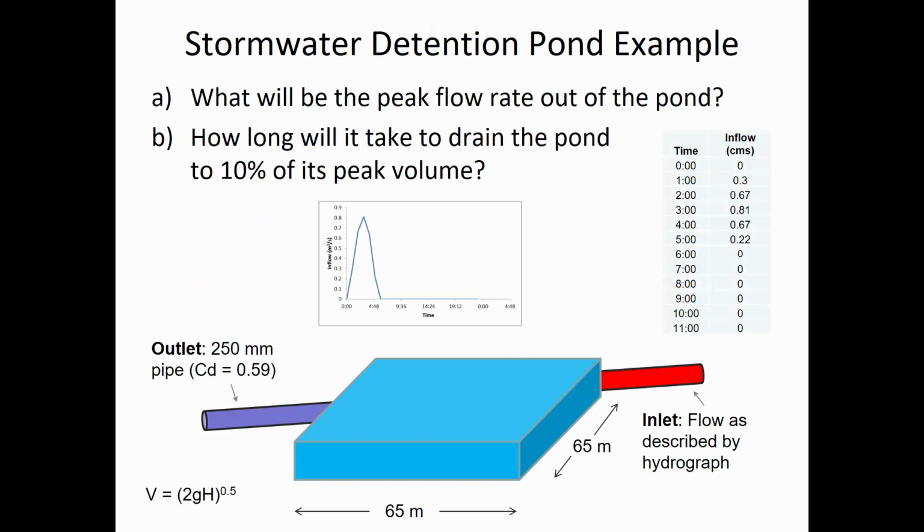Okay, so here's an illustration. We're going to go through and with Excel size a pond and find out what's going on here. Just for simplicity, let's assume that this detention pond has square edges. Now, that's not realistic, but the geometry is a little bit simpler for this first exposure to the method. More realistically, we'd have kind of a trapezoidal shape of a pond.